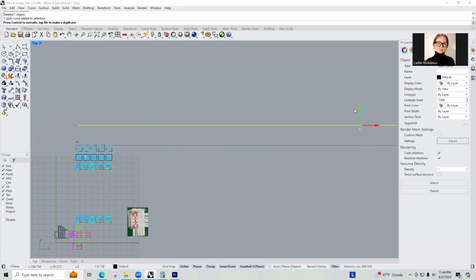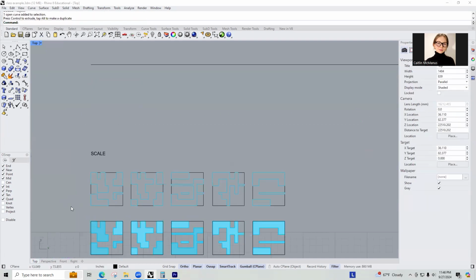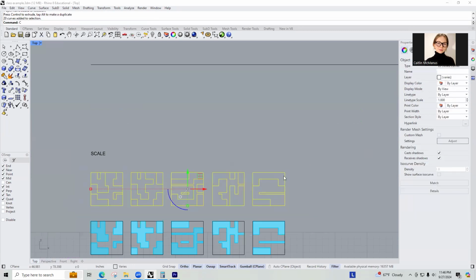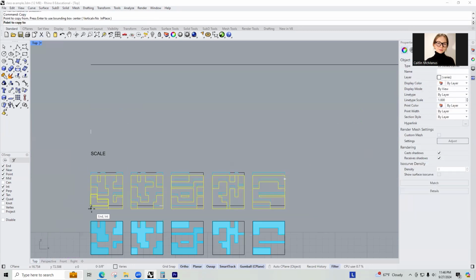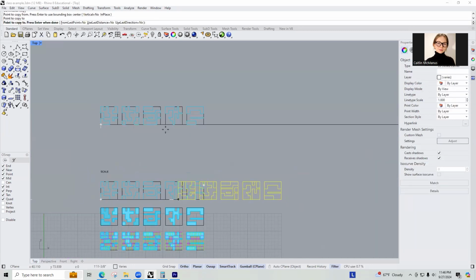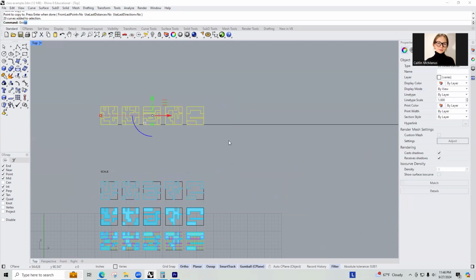All right, so now that I have my 40-foot line, I know that this is what I'm supposed to scale my boxes to. So I'm going to copy this group. I'll actually type group to keep it consistent. And then I'm going to scale. So I'm just typing in scale. In the previous assignment, we did a lot of scale 1D. This is just general scale.